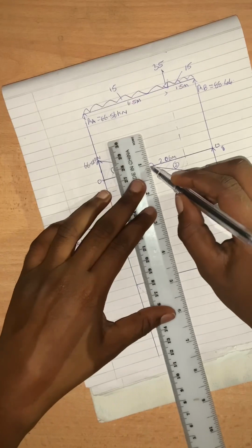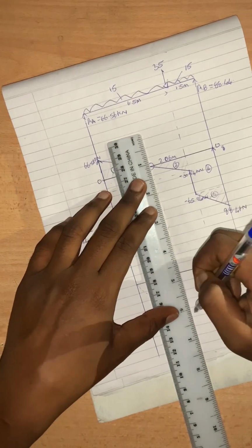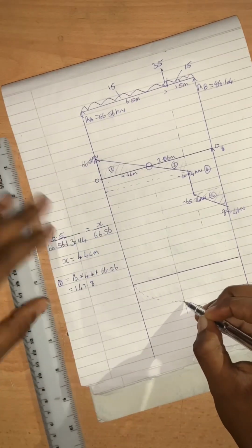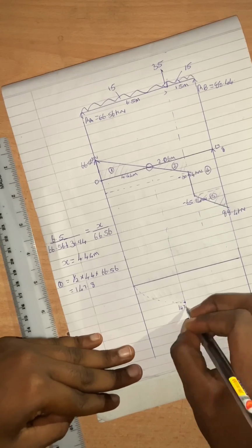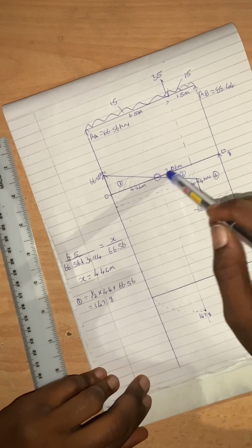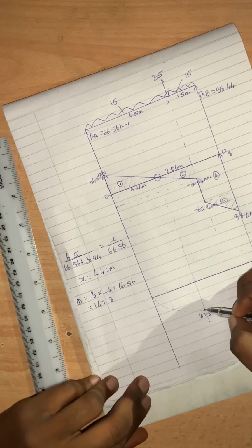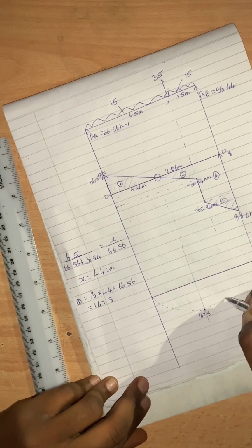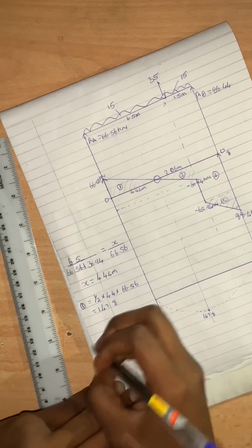It's right here. So we already have that maximum point, which we have here as 147.8. So when you start taking the area, you realize that the area of these places will be negative, because it starts to go up. So your bending moment diagram is something like this. Let's just do it for the rest of the shapes.